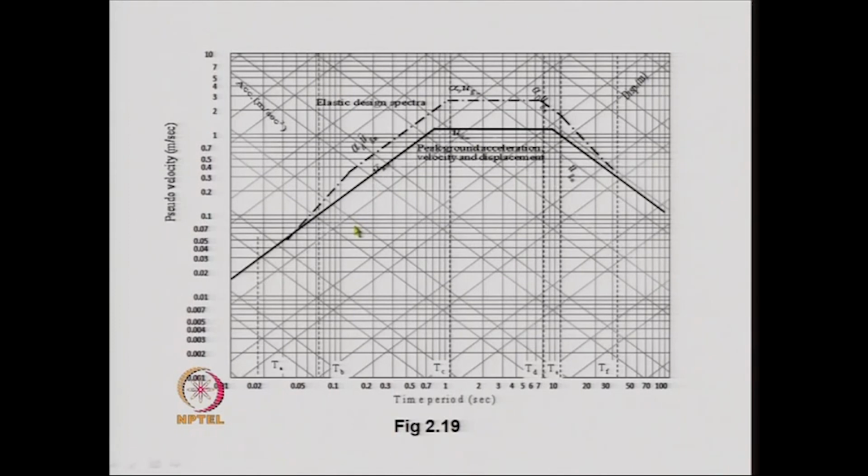Now let's look at how we can obtain, using the steps, the response spectrum in a tripartite plot. This is the baseline. Baseline means the maximum ground acceleration that is plotted over here, and it is parallel to the SD axis, and we measure the acceleration along this line.